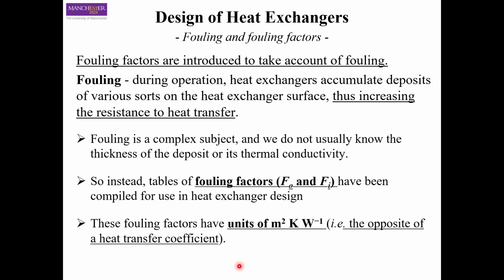So one easy way to look at fouling is to use fouling factors. Okay, so people have developed these fouling factors over the years for different systems, and these fouling factors obviously depend on a range of things, like what kind of feed you have, what kind of flows you have, what kind of temperature and pressure conditions you have. So these are all accounted for in these fouling factors.